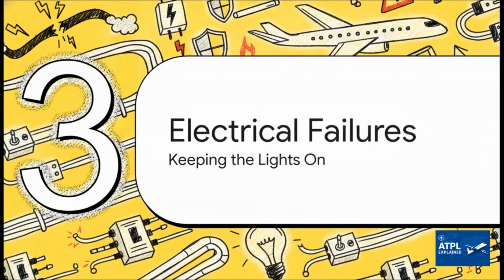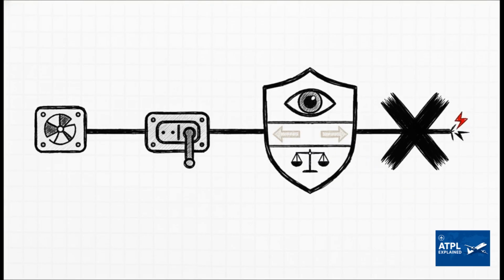Okay, Part 3, electrical failures and protections, keeping the lights on. So what would you actually do in a failure situation? To figure that out, we need to look at how the aircraft actively protects itself from electrical fires and shorts. There are two essential components you've got to remember here, the GCB and the DPC. The generator circuit breaker, or GCB, connects the generator to its bus. Now, don't let the name trick you, it's actually a heavy-duty contactor, not just a standard little circuit breaker protecting a single wire. Then we have the differential protection circuit, the DPC.